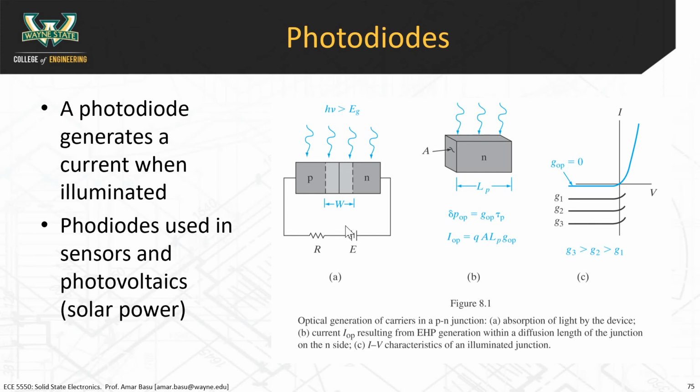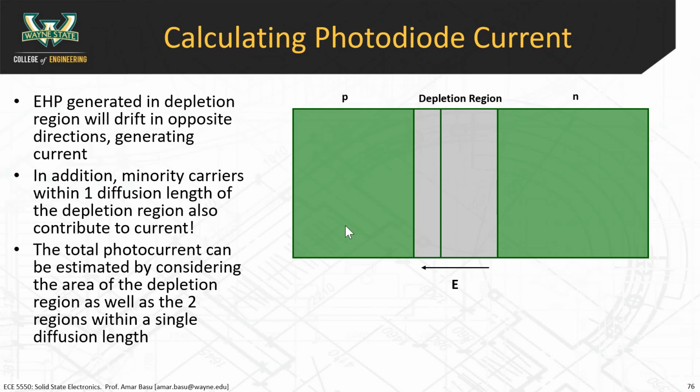The key thing at the photodiode, now you have a PN junction. You have a P-type material and an N-type material together, and that turns out is what allows you to actually generate power when you hit it with light. And so this is a really cool phenomenon. So I'll draw a little diagram to help explain it. This is based on things that we already understand, fortunately. So understanding how solar cells work is actually within your purview already.